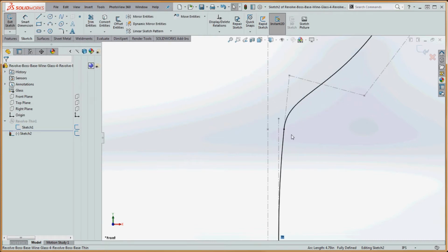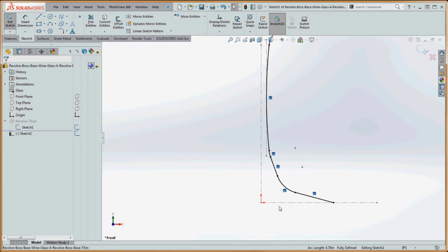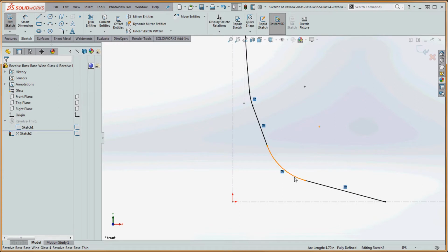So what we want to do is close the hole, and we're going to do that with another Revolve feature. We're going to take an arc and go from this line, tangent to that arc over here, that spline, and put it onto that center line. We're going to make the center of that arc right on that center line, so it's going to have a nice smooth transition up here. Then we're going to do something very similar down here, probably take it from this arc, another 3-point arc over here, and plant it on that line so it looks like a smooth transition down here too.